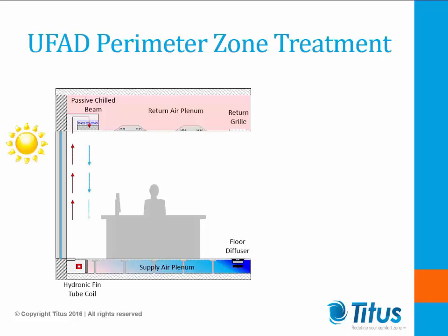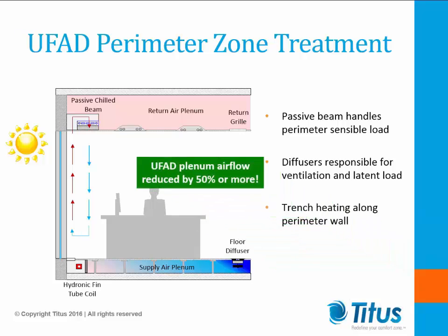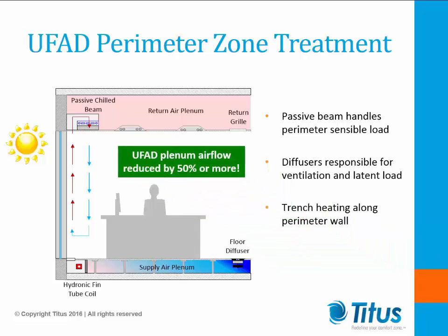The concern now becomes the potential for higher moisture content in the supply air. The supply system must reduce relative humidity to less than 60% to meet IAQ, indoor air quality, concerns, and this requires dew points of less than 65 degrees Fahrenheit. Potential solutions are either reheat or blending of air to achieve a 65 degree supply, 55 degree dew point condition.